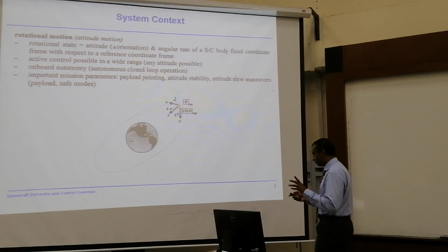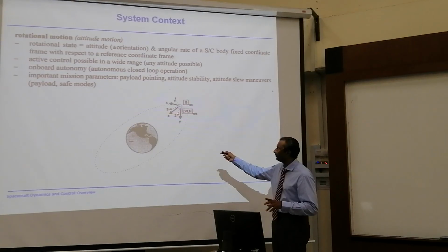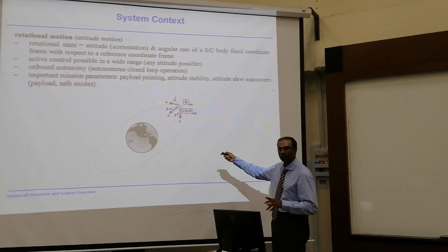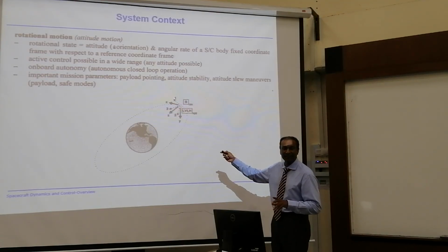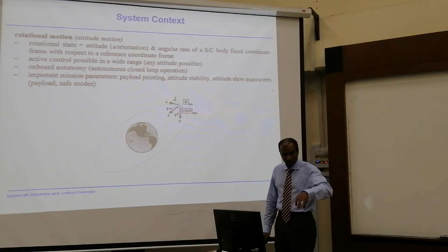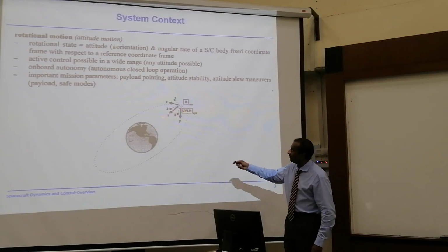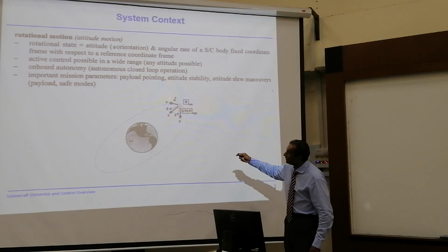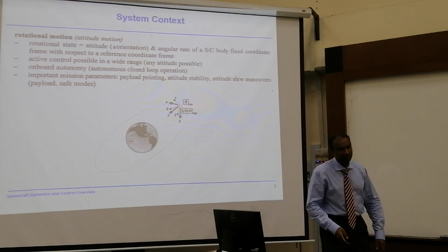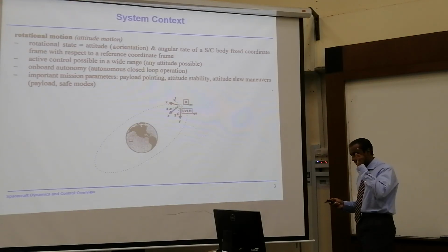Okay? So please understand, two coordinates are involved here. Local vertical, local horizontal. So this I can define for you now. This is your pitch, roll. Roll is the flight direction. So please do fix this. This is for attitude control. Fix this always. And yaw will always be facing here. And roll will always be tangent. If it's a circular orbit, it will be tangent to the orbit. That is done. So local vertical, local horizontal is done.